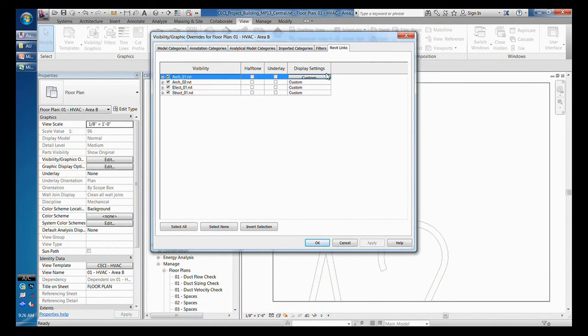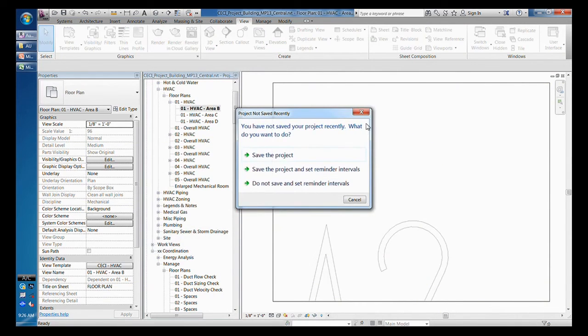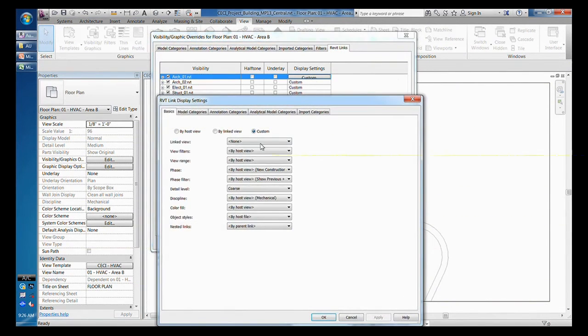There are all kinds of elements that there is no way of managing through visibility graphics unless you map to a specific view. Unless you actually select a view from the architectural file, you cannot display hatches. You cannot display line work. You cannot display the grid bubble offset I showed you earlier. These things are a pain to manage because they're not something you can really manage globally. You've got to go into every single view. And this is where our guys have wasted a ton of time.